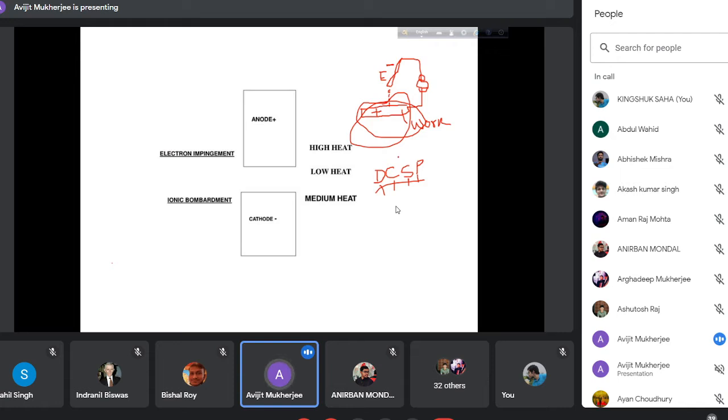So what to do in that case? In that case, the work should be connected with negative polarity, and the electrode is connected with the positive terminal. So maximum heat will be generated here. This will be melted at a very high rate. No harm. Droplets will be deposited, but less heat will be generated here. So this will not be melted rapidly.